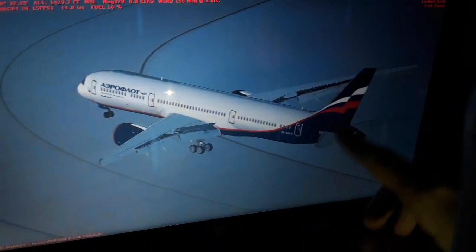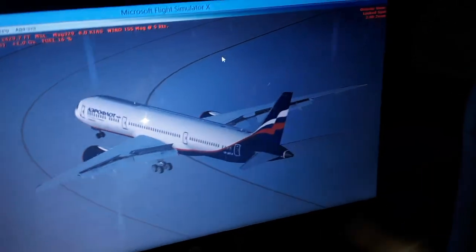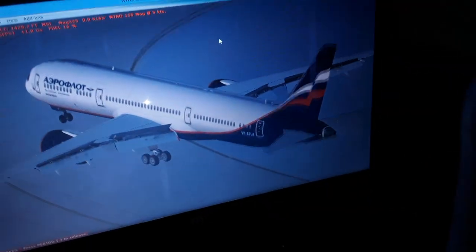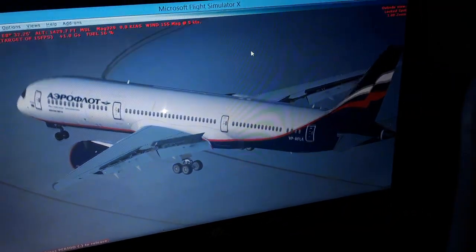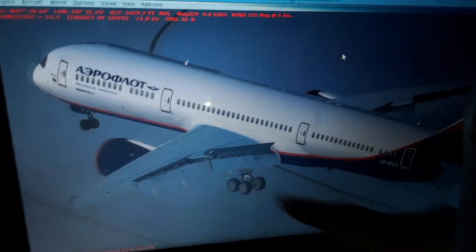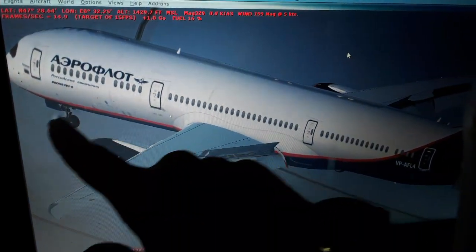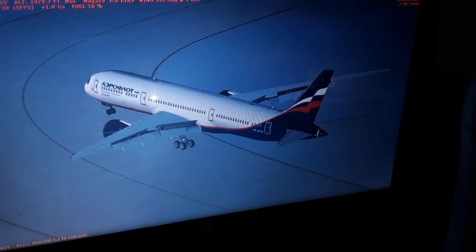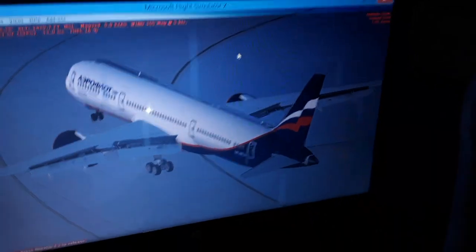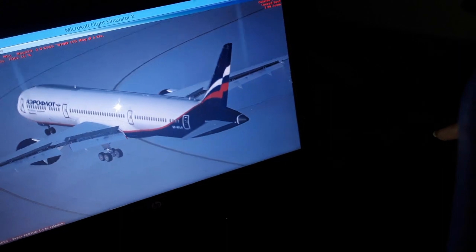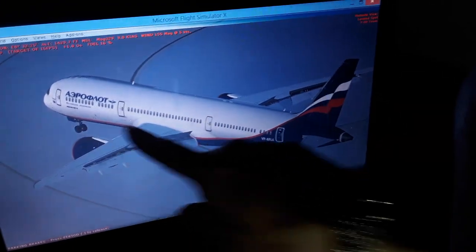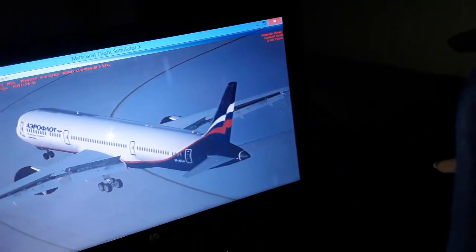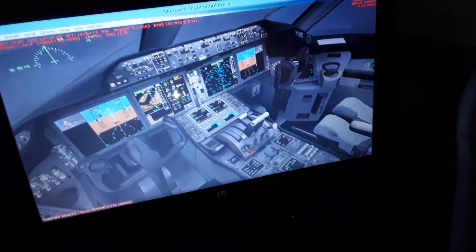Then above 80 knots or 144 kilometers an hour in takeoff, the computer will automatically lock the forward nozzle to 0 deflection or a small deflection like half or 1 degree. So we have only the rudder above 144 kilometers an hour or 80 knots in takeoff. Also when we land it's the inverse: we're slowing down the aircraft and then the computer will automatically activate the forward nozzle. So this is for the rudder pedals deflection.